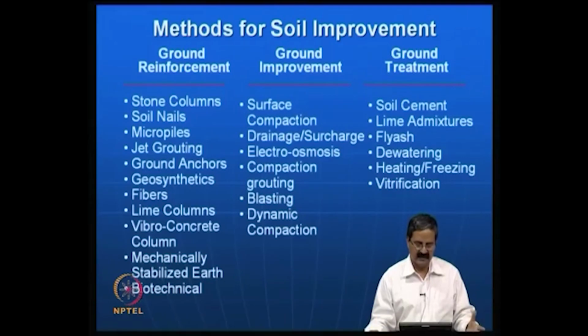What happens? Because of the energy, the whole soil gets consolidated or compacted in a very short time. So, blasting is another technique people have used. In fact, in liquefaction problems, this is one of the techniques experimented with a great deal, because it is a very useful and simple technique to use.